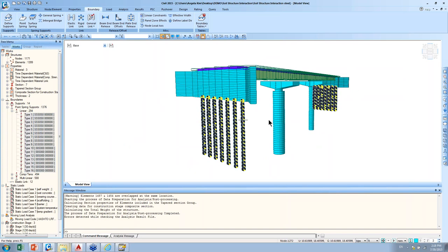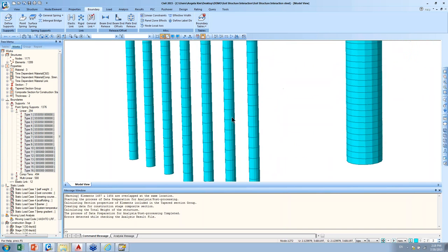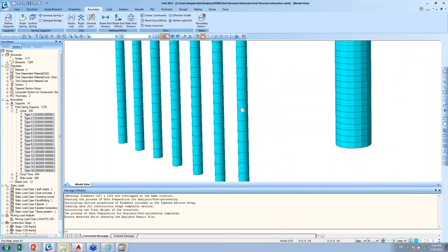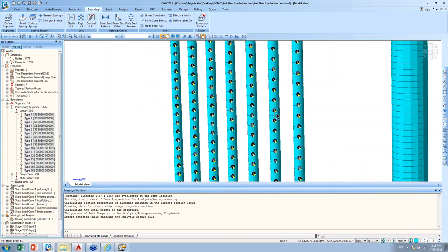The linear springs are applied for the vertical on the pile. How can I tell the components are applied in the vertical direction? The symbol is a hexagon made of 6 triangles, each going clockwise from the north, representing dx, dy, dz, rx, ry, and rz.